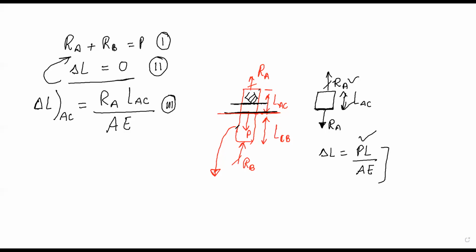Assume as if the external load P is not acting. Isolate this RB out. Therefore, as we isolate this portion RB, on this element the load acting is RB in this direction. This length is LCB. This portion will be in equilibrium when we have a load acting in this direction such that it is also equal to RCB. We don't have to take the external load P into consideration right now. Why? I will discuss that later on.